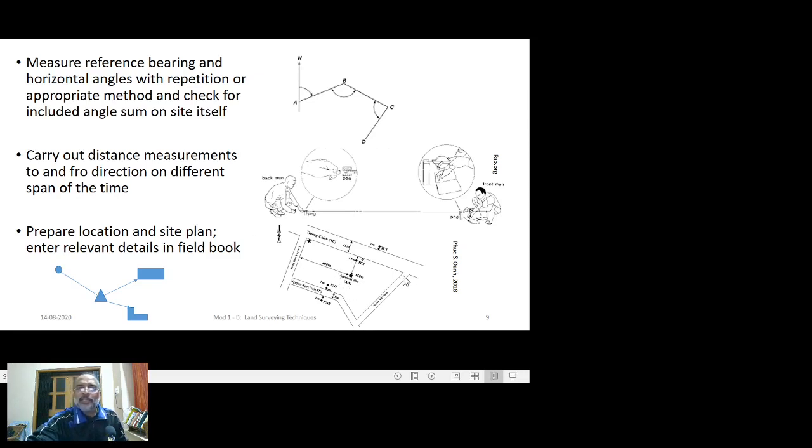In addition to this, one is supposed to prepare certain location sketch. So the way you see, this is the station, or rather it is one of the stations that is used for establishing the control on piece of the land. So for that particular station, we have to make use of two independent measurements to plot that particular station under consideration. And in order to confirm the location, here we can make use of certain, say, third measurement.